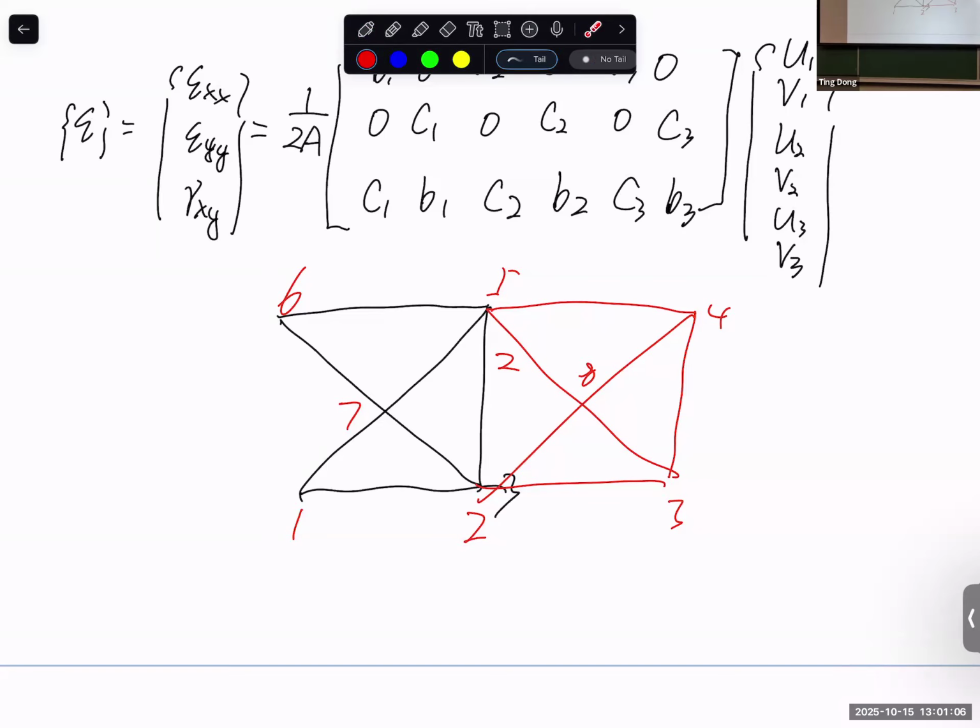Which type of stress do we report with elements? Like we don't report von Mises stress, as no specific one is specified. What did the problem statement ask? S11? Element stress. So this is a truss problem, right? S11 means sigma XX. So it's the actual stress.